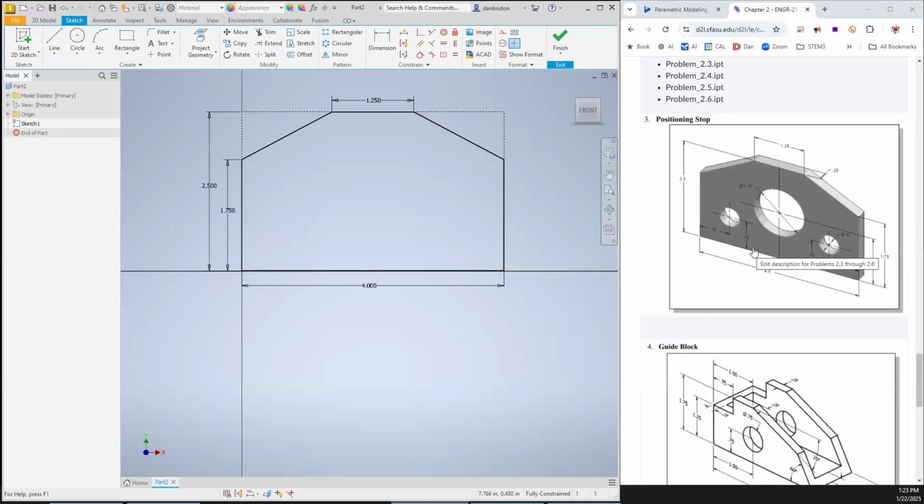So it looks like it's going to be 3/4 of an inch in from each corner. So let's see, what if we just draw a random circle? We don't want any of these locks to take place. It just really needs to be floating out here in the middle of nowhere. You saw that it automatically tried to make a center alignment there, so we want to make sure there are no dotted lines when we do this. Then we can start constraining it.